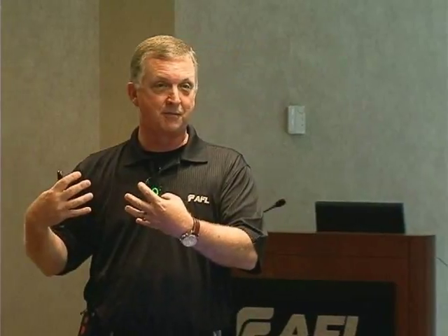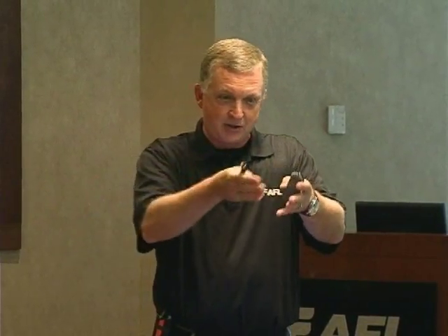If enough people call in a given area, I can use the analytical capability of my systems and say, based on all these callers, it looks like it's either this device that's failed or this switch that's opened. Then you can manage your workforce a lot more efficiently: send one person to one place instead of sending 14 people out to find where the power might be out, where the tree's down or somebody's run into a pole.